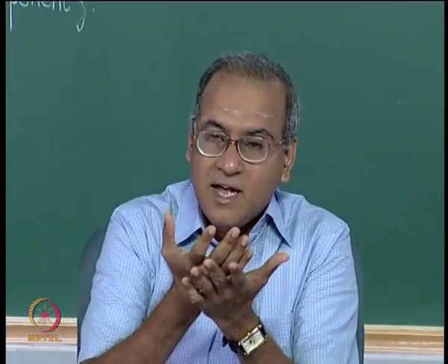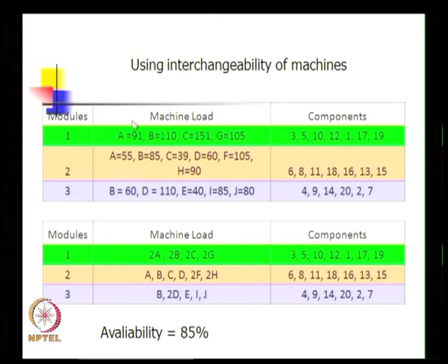So again, we will have no other alternative but to start looking at other places where machine A is available and we start creating intercell moves. For example, if this 91 becomes say 110 and 55 becomes 65, that 10 we certainly do not have capacity for because we have only one machine. So automatically we will send that much of intercell move to the next cell because some capacity is available.